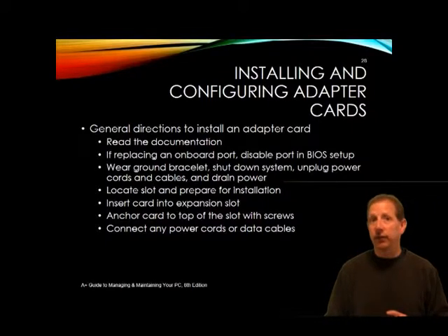Always wear your grounding bracelet to protect yourself against ESD. Shut down your system. Unplug the power cords and hold in the power button to remove any residual electricity.